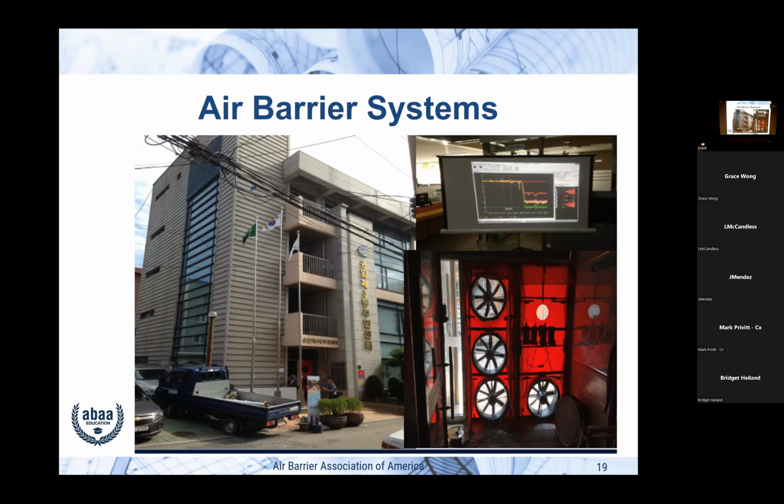So we set up, we conducted a test, and we went from room to room, looked at where the air leakage was. We wanted to accomplish two things. We wanted the people to understand that the whole building test is really not that hard. It's not some mystical thing that you do something to it and so on. It's pretty straightforward. And if you use things like smoke and so on, you can see the air leakage, and then you start to understand why. Where's that hole coming from? Why is it coming through there?